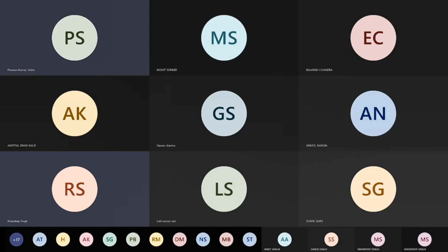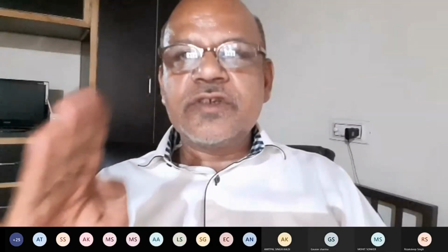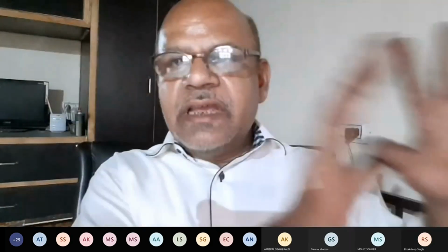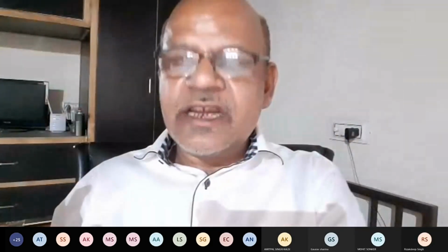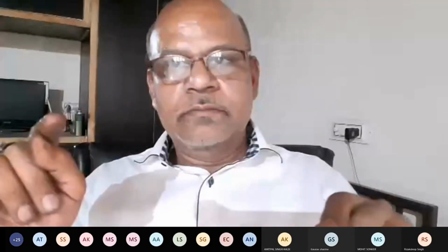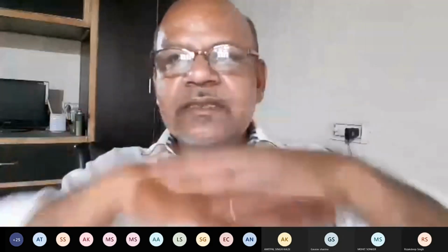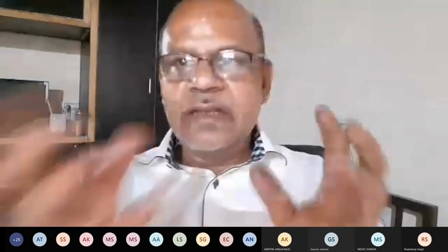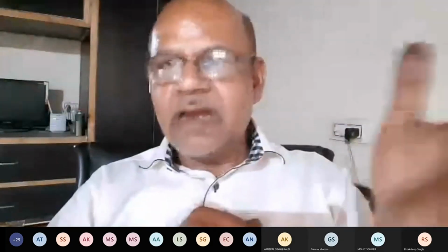Yes, it will become difficult because as we were talking about in the morning, the performance of the echo sounder depends some on the equipment and some on the external conditions. There we clearly wrote the seabed. If the seabed is muddy, the surface is soft and the reflection does not take place so well. Think of a rubber ball. आप एक दीवार पे फेंकिए, वापस आती है. दीवार being hard, it reflects the ball very nicely.